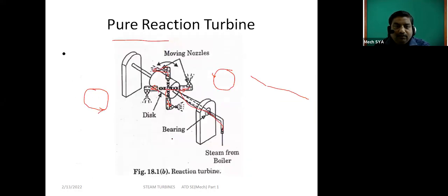And reaction turbine, the Parsons turbine. So what is happening in the reaction turbine? Partially the pressure is decreasing in the stages. Some amount of pressure decreases in the nozzle, but afterwards not all the pressure is converted into kinetic energy. During the stages the pressure decreases continuously. Okay, correct, very good. So I think Asmita has written. Here the pressure is decreasing throughout the stages. Not only in the nozzle, it is also decreasing, but the more significant part decreases in the nozzle.